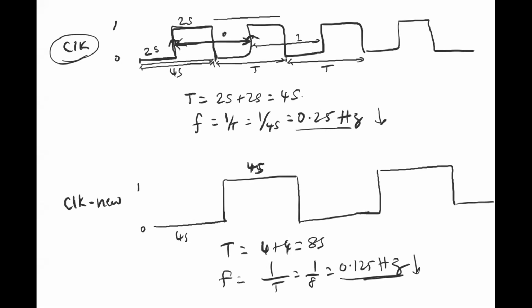And you already have a piece of Verilog code that will tell you the number of cycles of your clock, because that's what you designed in week one. So you try to design something which will give you a number for every clock edge that you're generating.